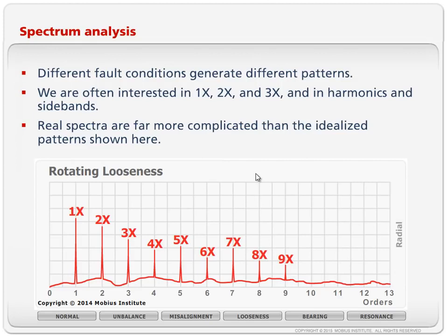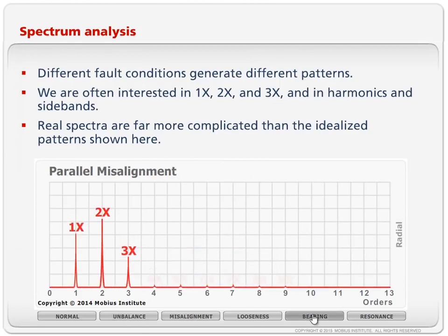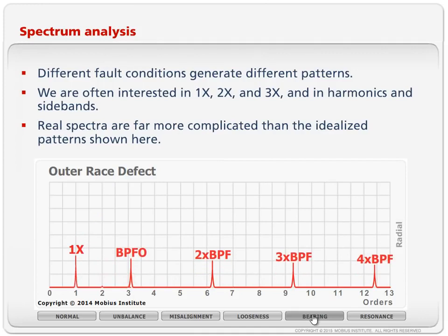And if you understand why the vibration changes the way it does, then not only do you make sure that you set up the analyzer to capture that vibration and you take measurements in locations that will capture it, when you see patterns like this or patterns like that or patterns like this for bearings, you won't just think of the wall chart. You'll think, aha, harmonics, what does that tell me?